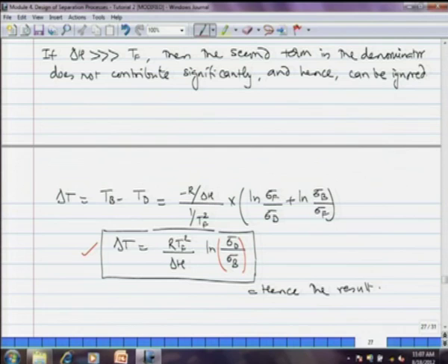Such an expression is very handy for heat integration of the process, where you want to integrate your distillation column with other process streams, or integrate two columns in a sequence. As I said in the previous lecture, you can do that by varying pressures of the two columns, so that the vapors of the first column condense in the reboiler of the second column. So these expressions are very handy for making such energy integration matches.